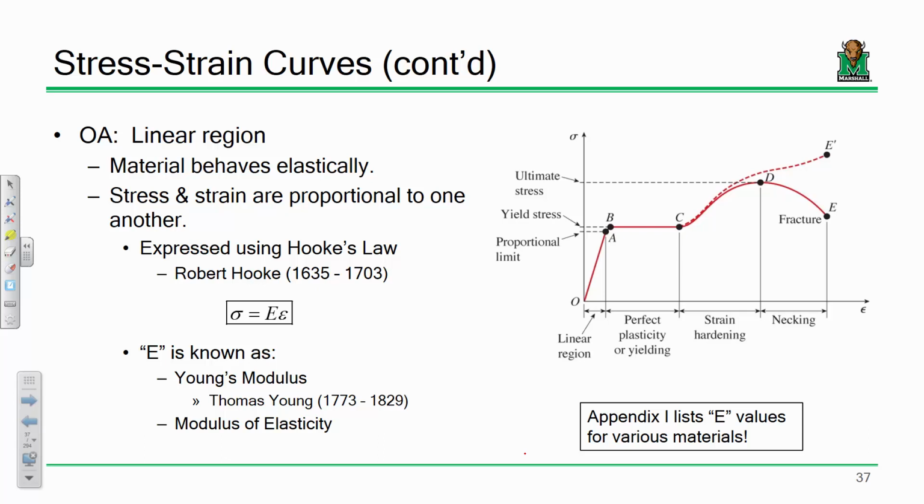So in most cases, we like elastic behavior. In design scenarios, you're going to see us refer to elastic behavior quite a bit. That's why we want our systems, once they unload, to go back to the way they were. It makes the behavior more predictable and what have you. Now, let me be clear. That's not always the case. There are some instances where we prefer inelastic behavior. There are some very specific instances. One instance is, for instance, in vehicle design.